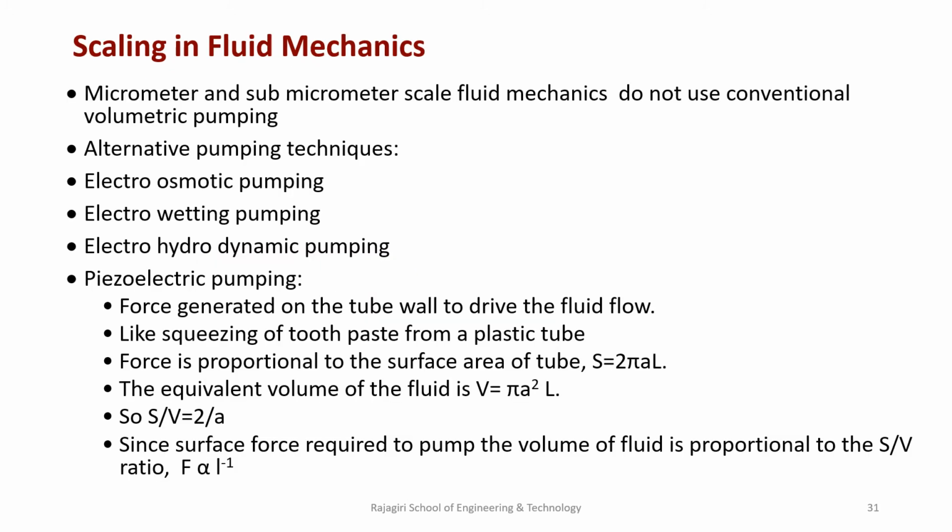As discussed just now, it is extremely difficult to push fluids through microchannels because of the large pressure drop. So micrometer and submicrometer scale fluid mechanics do not use conventional volumetric pumping. Some of the alternative pumping techniques that are used are electroosmotic pumping, electrowetting pumping, electrohydrodynamic pumping, and piezoelectric pumping.